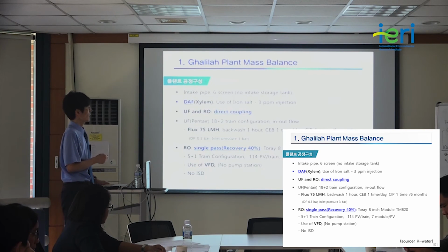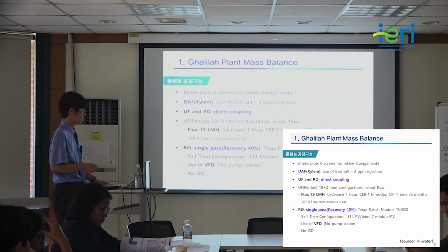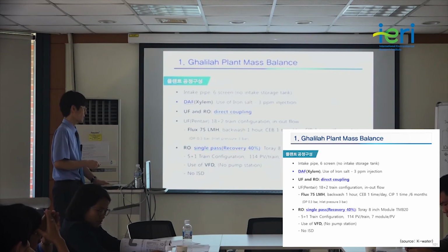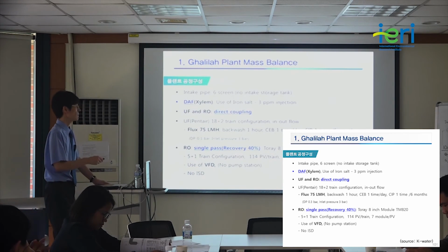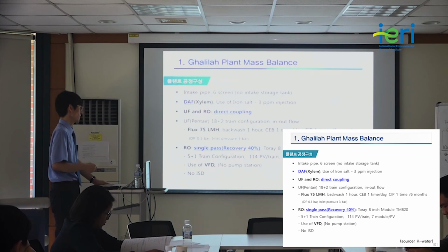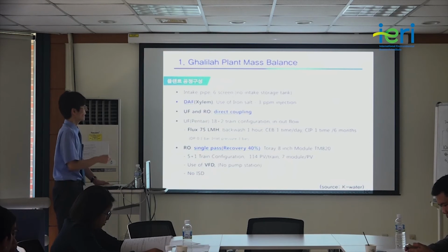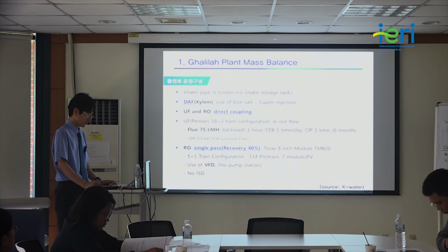The only thing that can be seen here is they have the inlet pressure of 3 bar and differential pressure of 0.3, and 3 bar is a slightly larger value. For reverse osmosis, the conventional recovery of 40% was adopted, and the membrane was not really special, and they used VFD, but they didn't use any pump station, and no ERD was adopted. So again, it's not a really special design or special configuration.